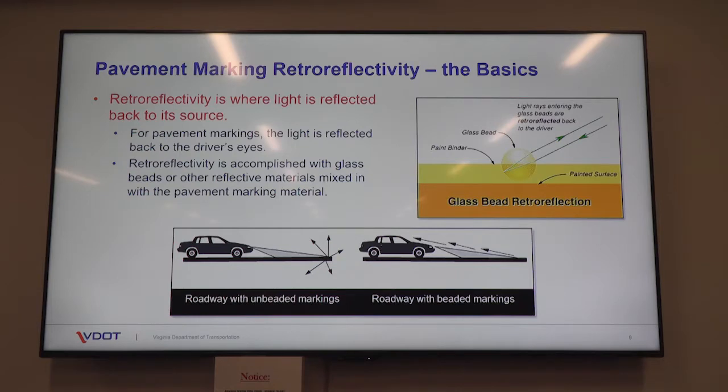There wasn't an analogous or similar requirement in the MUTCD for pavement markings, because at the time, measuring retroreflectivity in pavement markings was not really as far ahead as it is on the signs. There was disagreement on how to do it and what the threshold should be. So that, we understand, is changing with the next version of the MUTCD, which is anticipated in the next year or two. So there will be standards and thresholds for our pavement markings as well.